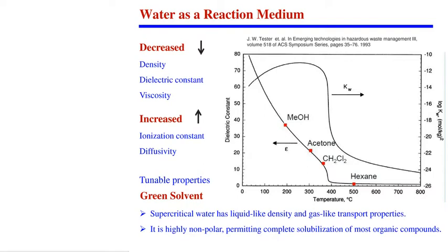If we are doing these reactions in subcritical water, that means water stays in liquid phase, so there is no phase change. If you compare steam at 250 degrees C, the enthalpy is 2.869 megajoule per kg. For subcritical water at 250 degrees C, we require 5 megapascal to keep water in the liquid phase, and the enthalpy is 0.976 megajoule per kg. So you can see that one third is required. Why this benefit? Because there is no phase change. So it may look energy intensive, but when you go deeper into it, you see that there is no phase change, so it's not an energy intensive process.